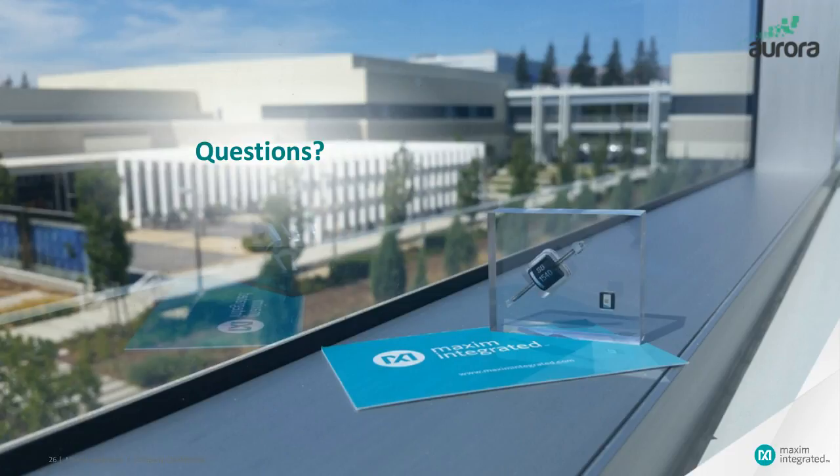And we have an algorithm that we use that is able to really efficiently find the maximum power point for that circuit. The parameters of that circuit are adjusted given the irradiance and temperature on the cell string, which we calculate using our shading engine.